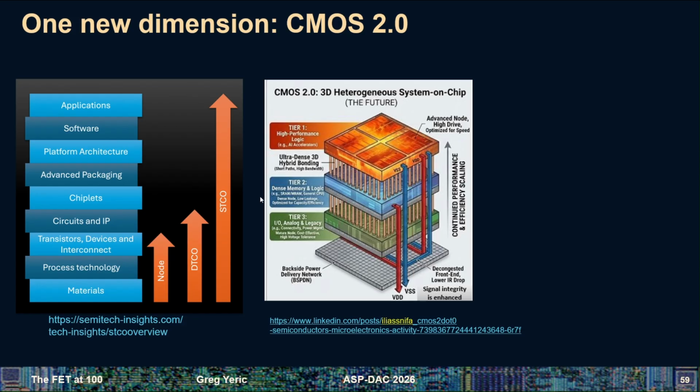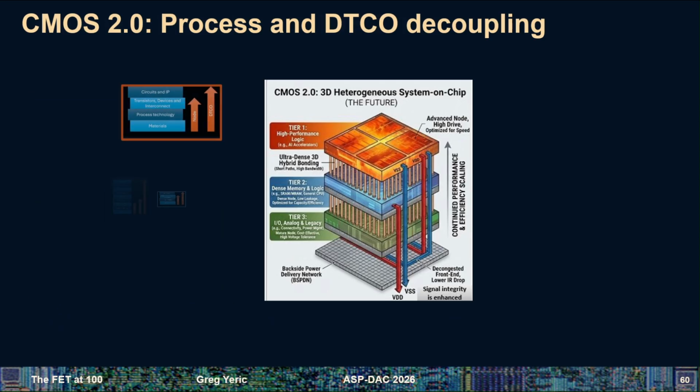At least at the circuit level, we would be designing circuits that are optimized around the particular transistors that we were using. And partitioning a system into chiplets, little tiny pieces, maybe incomplete chips is one way to think of a chiplet. So it's not a full CPU. It might just be the logic, or it might just be the memory. Anyway, we can break this into independent